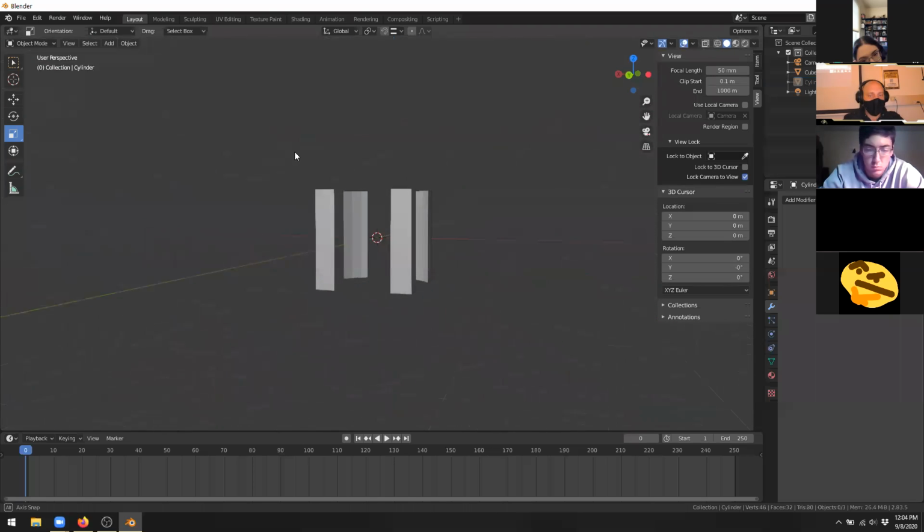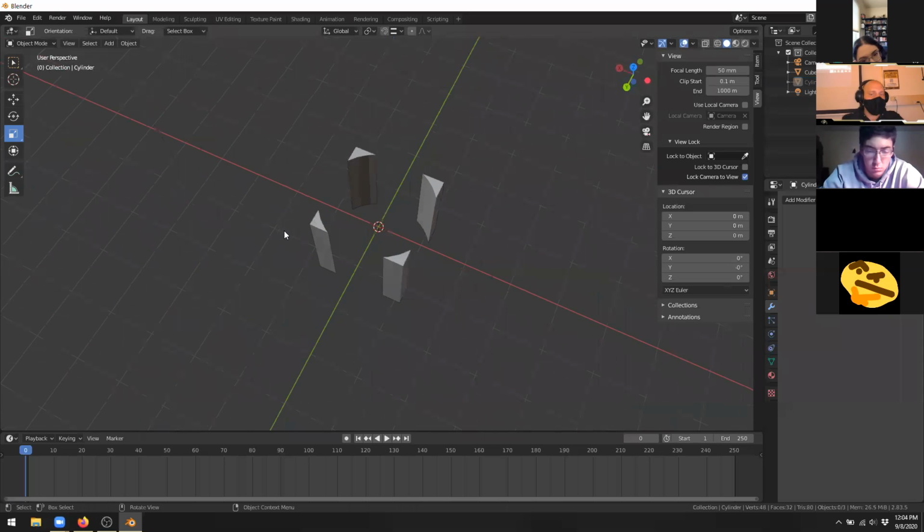it's almost like a couple of shards that are knocked out from what remains. And this is huge, right? This could be used just like some of the tools we used last time to help us craft new and unique objects that aren't available to us with simple geometry by themselves. Anytime you need to knock a hole out of something, the best thing to do is take a Boolean modifier, place some object inside of the thing you're trying to knock a hole out of, and then subtract it like we did right here.